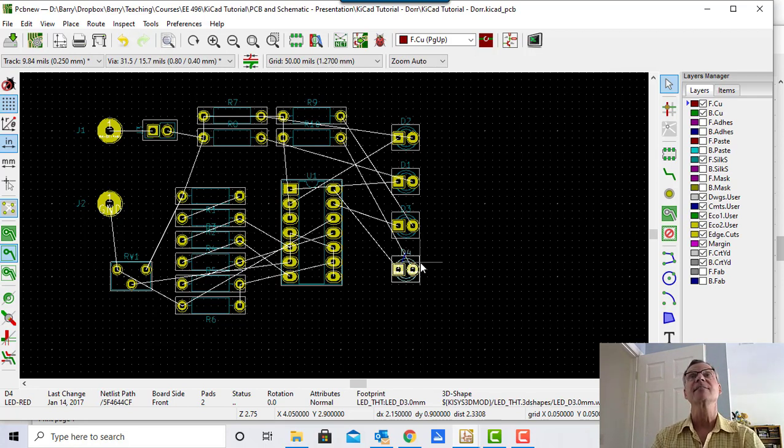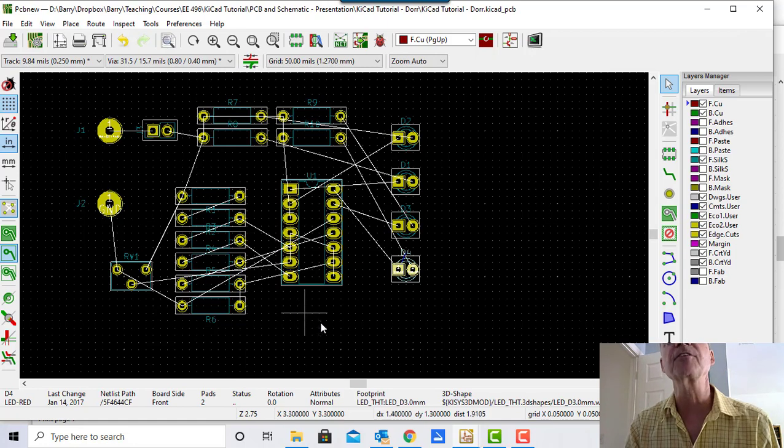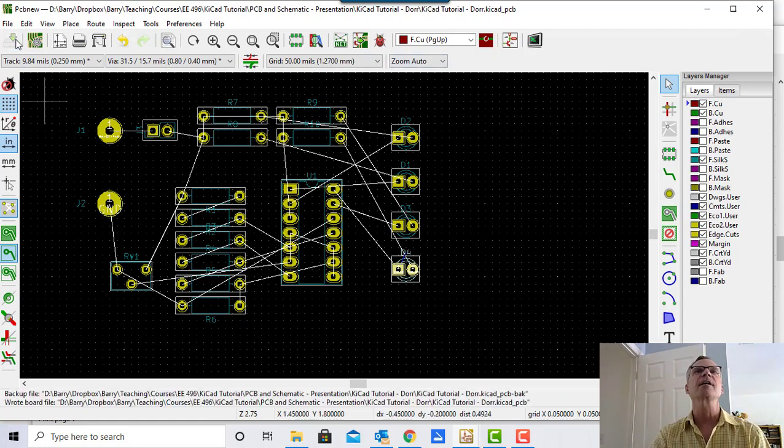The other thing is I don't have a filter capacitor. And on any design like this, you of course have filter capacitors in the power supply that's driving it, but we're going to go down through the wires into this board. I want to bypass that power supply right on the board. So oops, missed a component. So let's go back and fix that. So I'm going to save my work here because I don't want to throw this away.